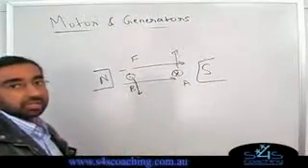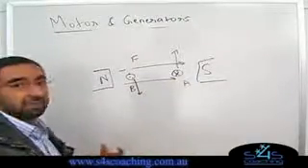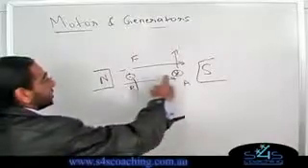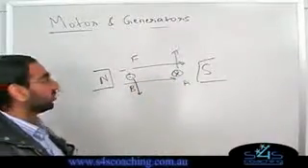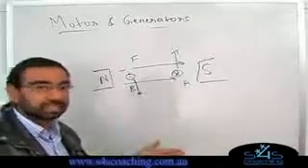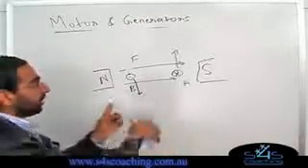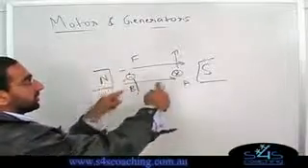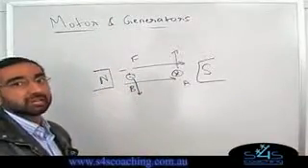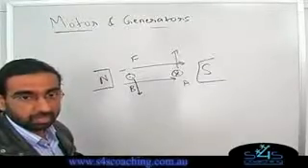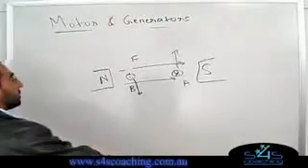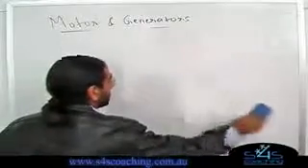However, if it's DC current, then what you need to do is have a commutator that is going to change the direction of the current every half a cycle. So therefore, for DC, I have a split ring commutator which can reverse the direction every half turn, and for AC, I just have a slip ring commutator. So these are the basic principles behind the operation of a motor.